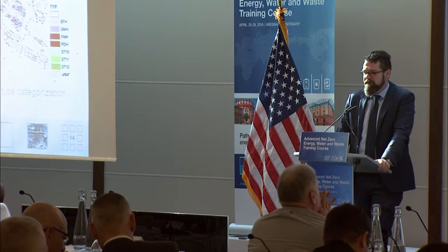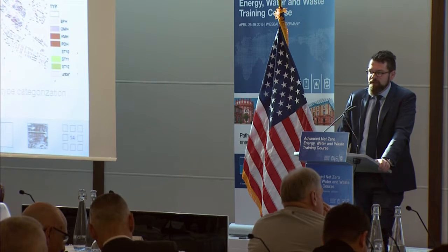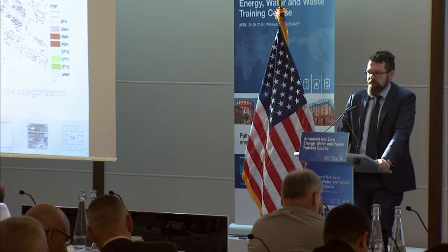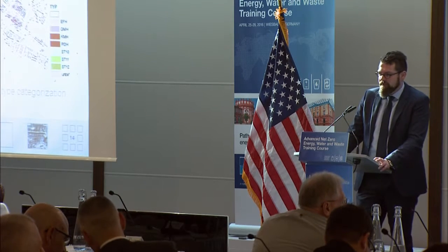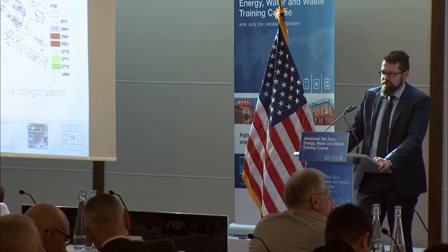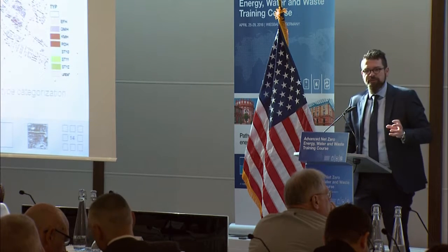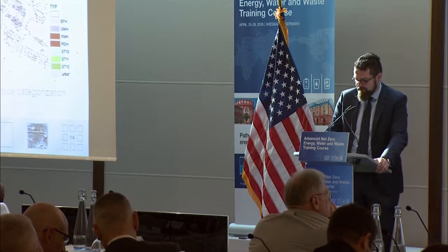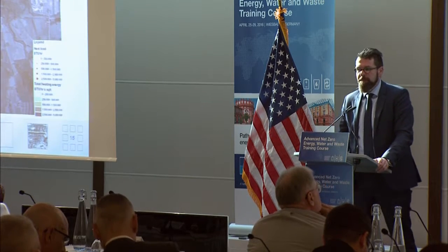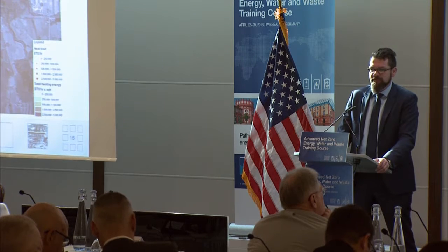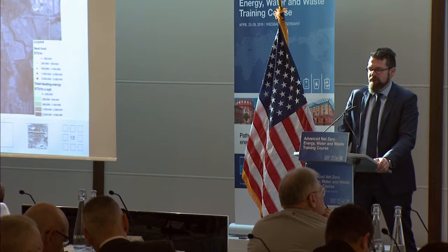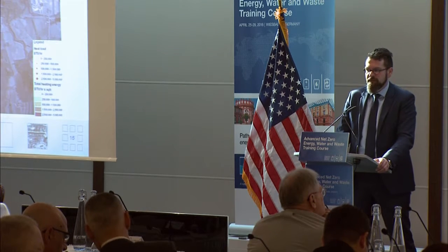In the figure on the right-hand side, you can see different kinds of building usages given by colors. The red colors are housing areas, and the yellow colors are different. You can't see those yellow colors quite well on this slide, but there are some different kinds of municipal areas with industrial or other uses. And then you can calculate the heat load of each building, and you can summarize it. You can see here each red dot is a building with a certain heat load.